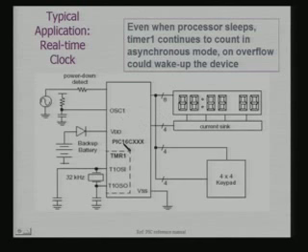So the processor is not doing anything normally. It just wakes up on getting the interrupt, on timer overflow, and updates the display. And the timer works on its own from an external clock source. So I can connect an external crystal to this timer as well.